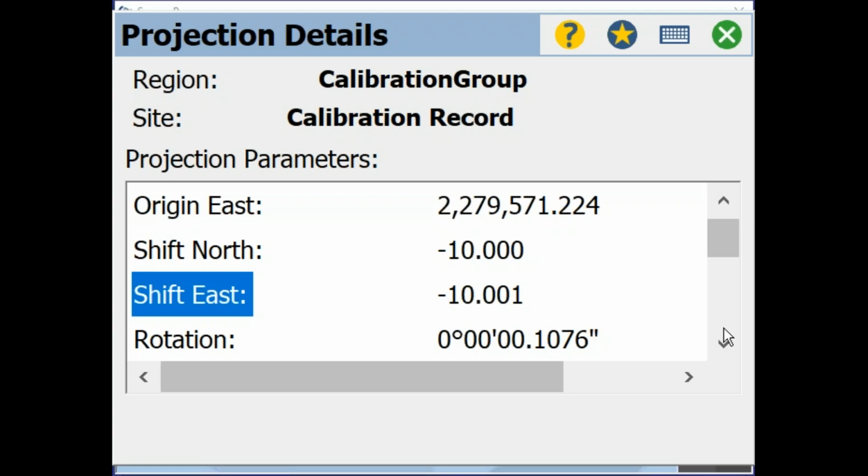Actually, no, I was going to say, remember, we're in a mapping plane case here, and I was using this special demo mode where I was feeding it canned coordinates. The coordinates I feed into it are the original control coordinates, the grid points that I imported. I shifted them by 10 meters north and 10 meters east, and then I generated geodetic coordinates from them. That's what I'm using for demo mode, essentially to simulate putting a GPS receiver on an autonomous position and starting from a here position, right?